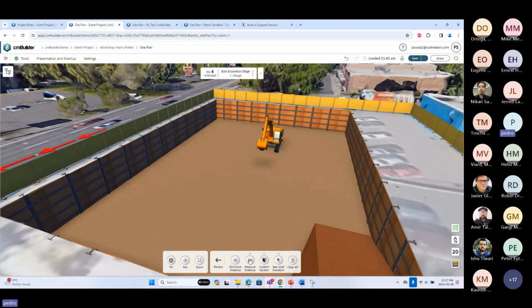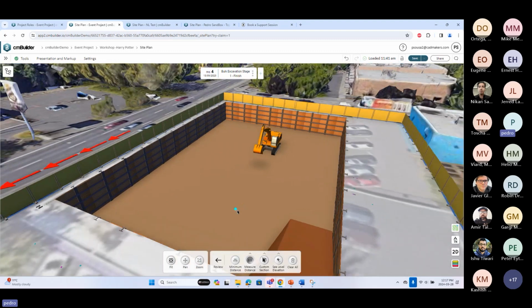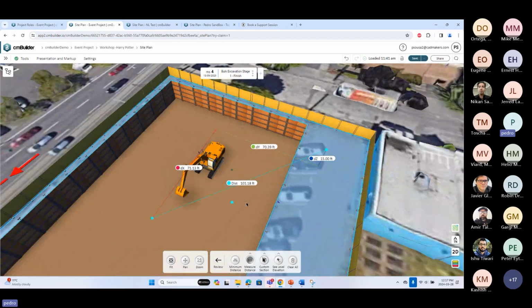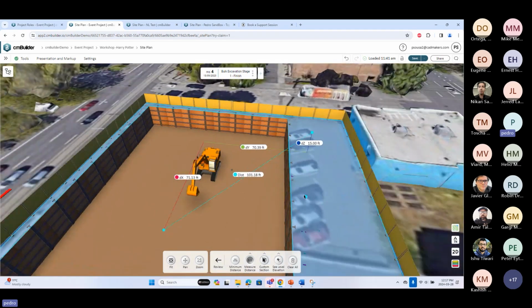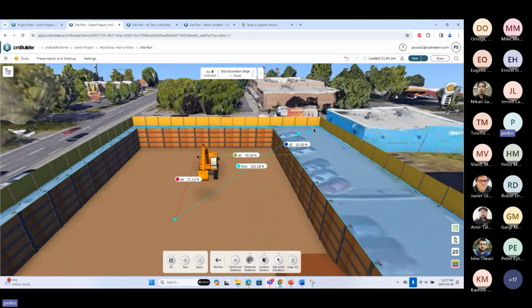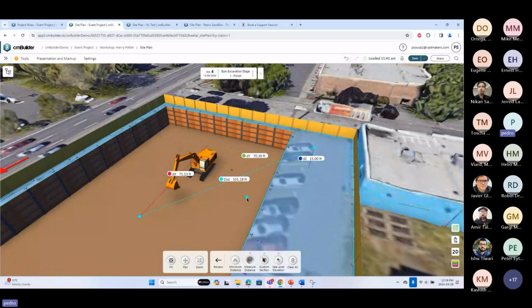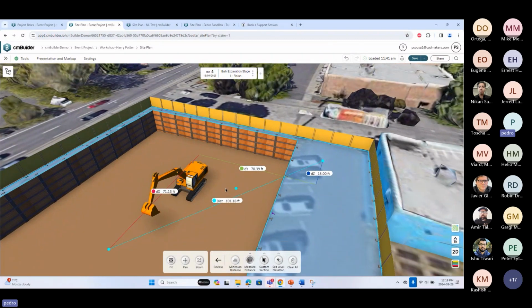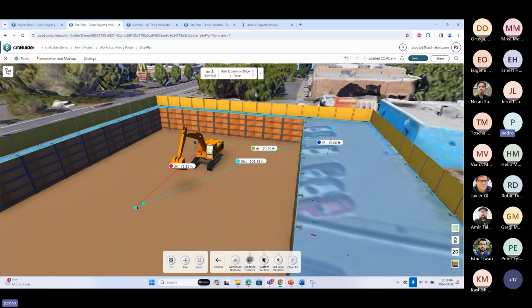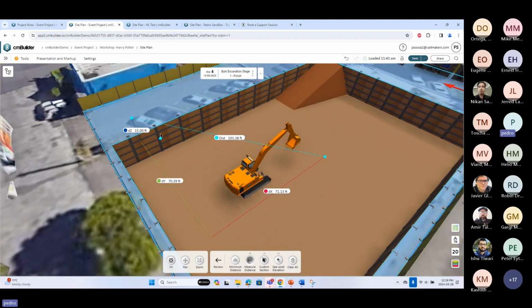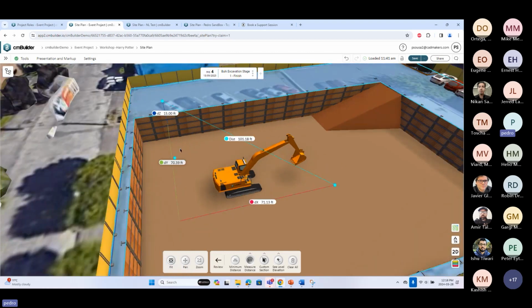And then we have the measured distance option. The measured distance will be a similar one, but the difference is that you are actually having a decomposed measurement for the distance between the actual points. This is now not point to surface. This is point to point, right? So it's the distance between actual points, like the straight distance. But also we have these components over here that are showing me what is the Z difference between this point, and the Y and X.